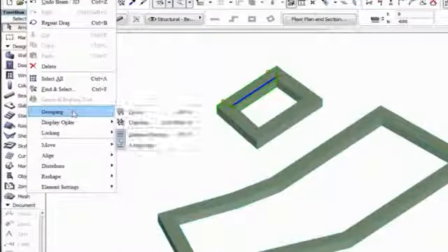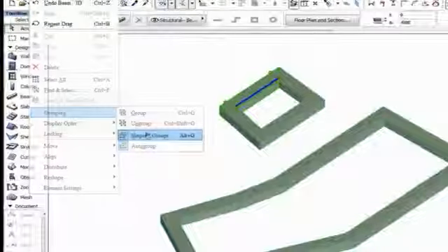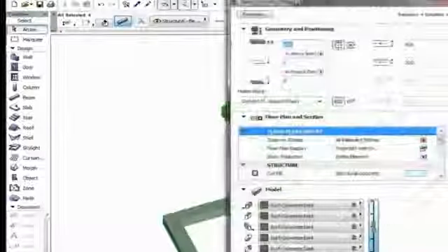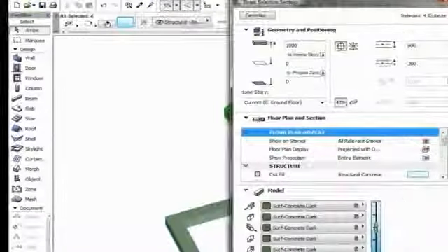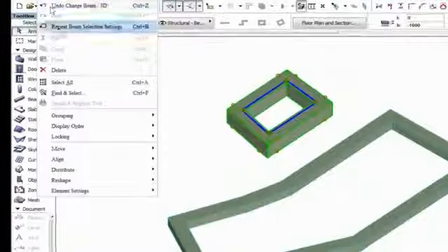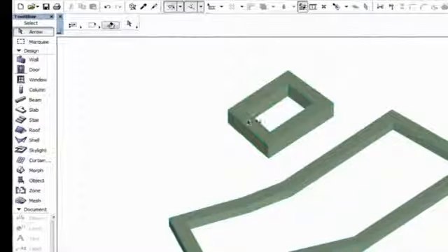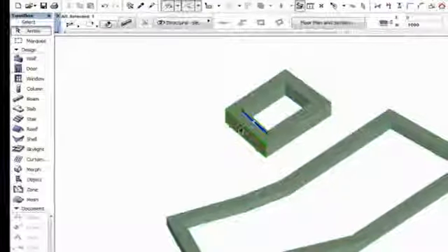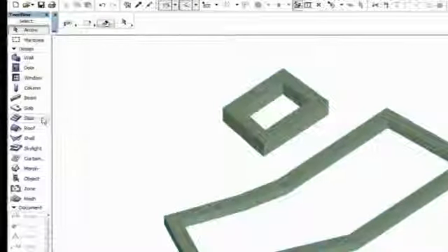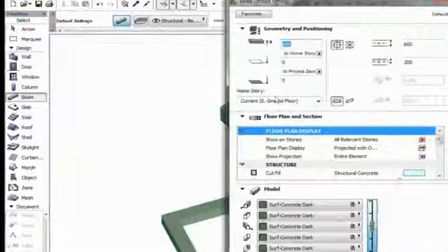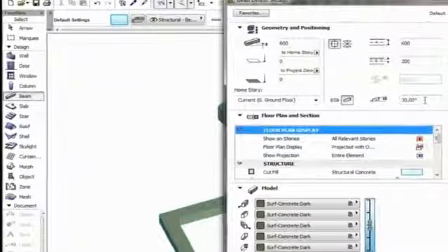Beams placed with these 3 methods are automatically grouped. Thus, you can select and modify the entire beam chain with just one click. If you wish to modify individual beam elements, just suspend grouping or ungroup the selection by using Ctrl-G for grouping and Ctrl-Shift-G for ungrouping. In order to create slanted beams, choose the slanted option and type the required slant angle.